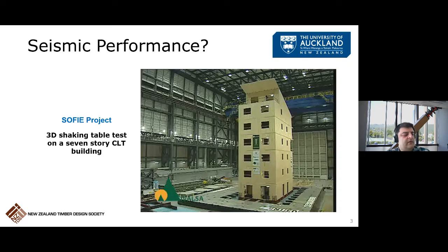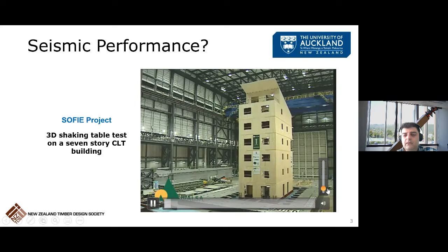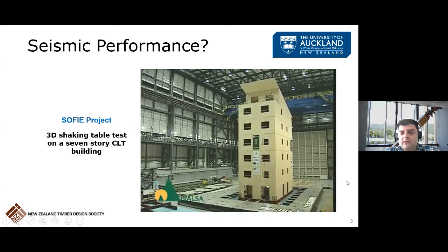There has been, in the last 10 to 15 years, lots of research going on to assess the seismic performance of mass timber buildings. The most comprehensive one, which I'm showing here as a representative for all of the research that was done before, is called the SOFI project, which is a 3D shake table test of a 7-story CLT building in the E-Defense facility in Japan. There's a short video here for the shake table test.